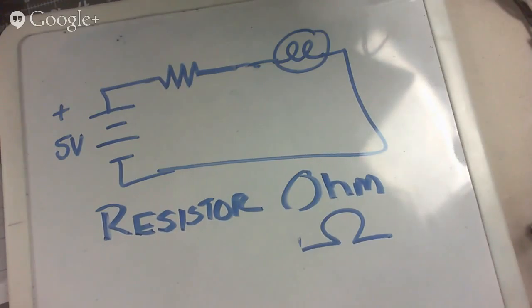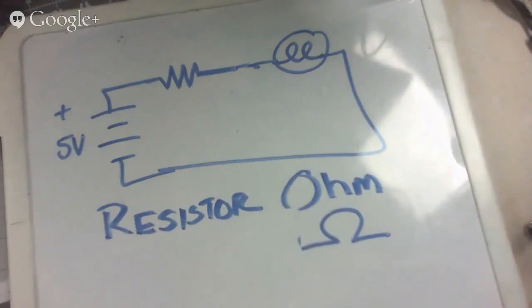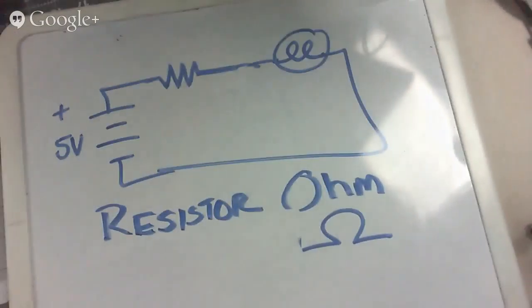It actually took me a while, well into my undergrad, to realize that when you do all the math and figure out you need a 327.86 ohm resistor, and you ask your technician for that size resistor if you're a new engineering freshman, they're going to laugh at you. Reality is resistors are only manufactured in very discrete quantities. So 220, 10 kilo ohm, 5 kilo ohm.